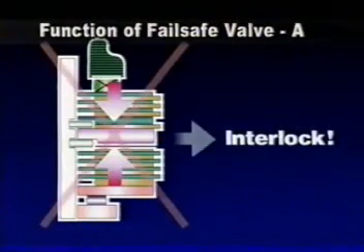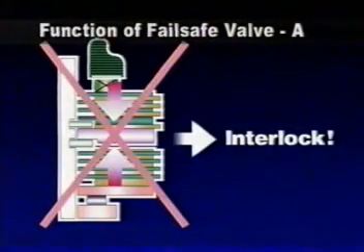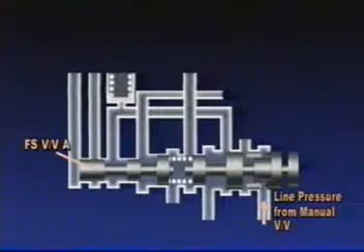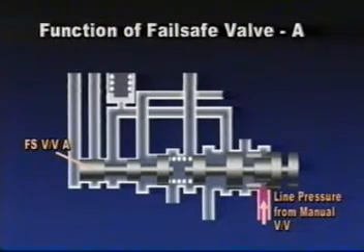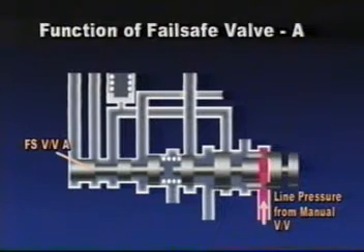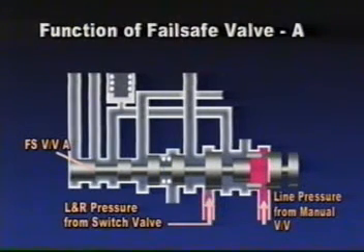If the oil pressure is supplied simultaneously to second brake and low and reverse brake due to the internal damage or breakdown of oil pressure circuit, oil pressure of low and reverse brake is automatically released by the hydraulic circuit of fail-safe valve A connected to each chamber.